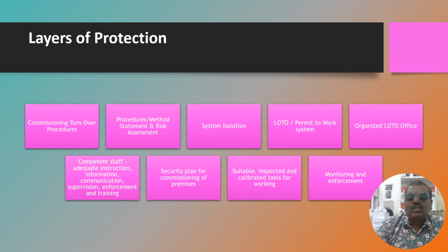Now, for example, the solo run test has been completed. So after the solo run test is completed, what is the second job? The second job is to be aligned with the pump. In this condition, a permit to work system should be implemented.